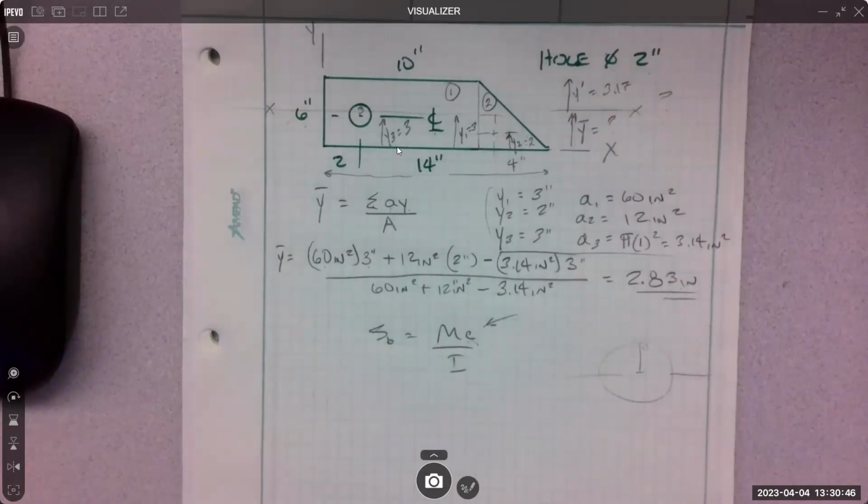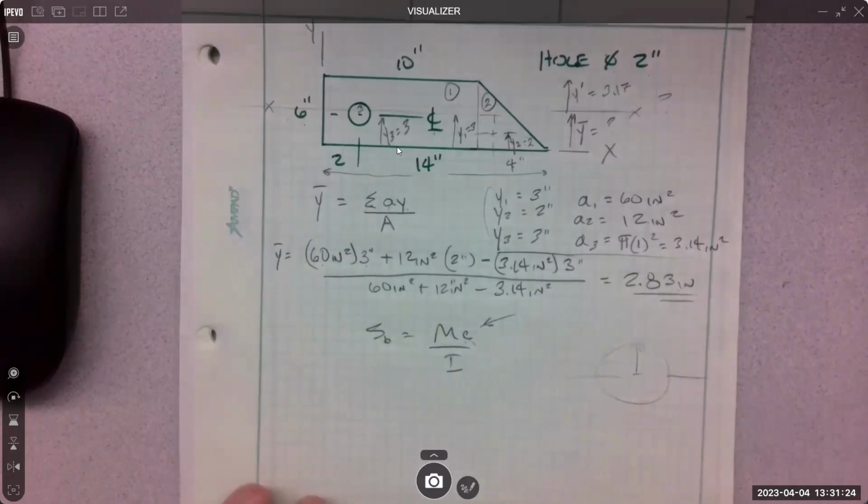It's the same process. We would only be interested in the Y if we had what's called biaxial loading from 2 directions, right? We're going to focus on single direction loading. We're not going to load it this way. And if you think about most of our structural pieces, like a floor beam has other floor beams, right? And we don't load those floor beams. We don't side load them. I mean, seismically, when the earth shakes, it gets loaded, and people with PhDs can figure that out. No, we don't need that stuff. Is that fair? All right.